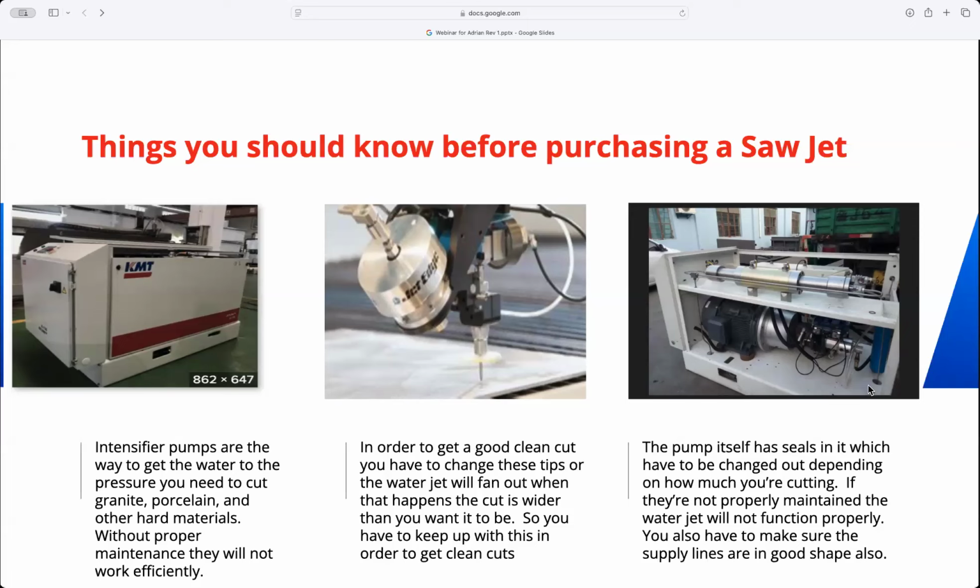Yeah. So if they're doing maintenance work on it, the clean out of the tank and so forth, then there's probably defined processes like turning off the power, lockout, tagout, things of that sort to help ensure safety. Definitely kill all the power and lock it out, so nobody can come over there and say, "Oh, we need to move this out of the way to grab this." No, you need to lock it out, and make sure nobody can ever get close to turn the thing on if somebody's working on it.